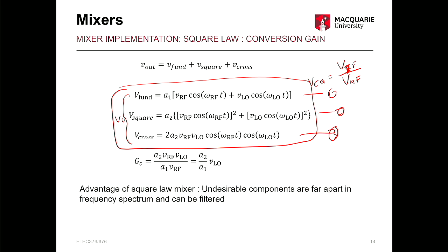And the other one, the V square, is the harmonics, right? Because it's the square, which will become 2 LO and 2 RF. They are individually squared, not the square of the whole sum. Okay, they are individually squared here and here, and this is the fundamental. So this is the IF. So the coefficient of IF is this one, and this is the RF.